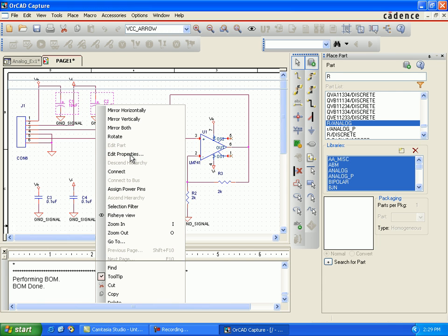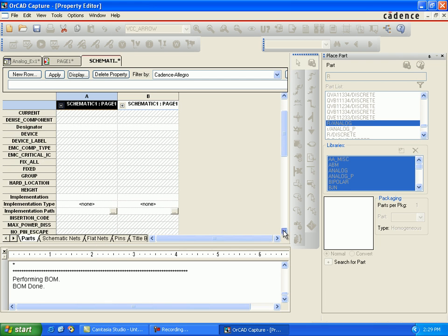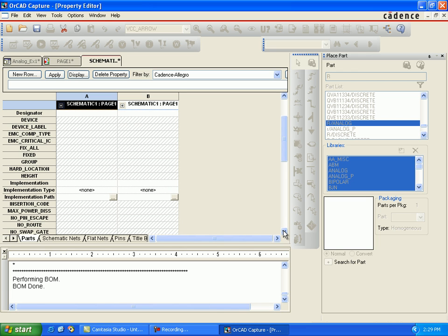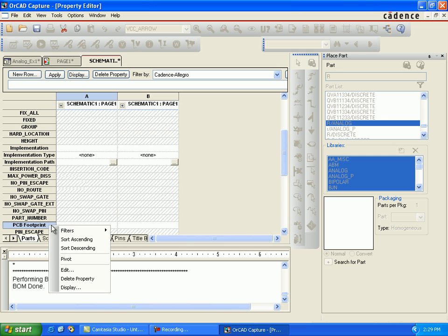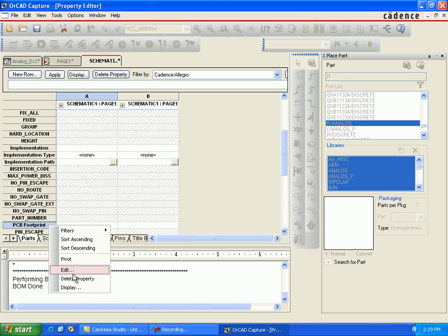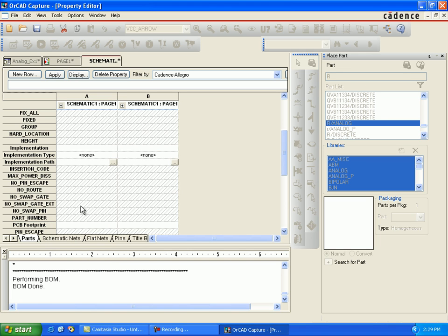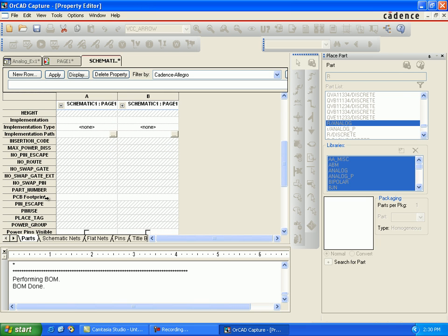First of all, select the capacitors C1 and C2. These two are radial capacitors, so I am going to use radial, which has 2 pins coming from the cylindrical head. Select both of them, scroll down. In the PCB footprint, edit.